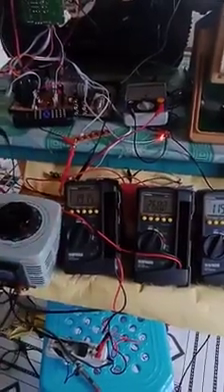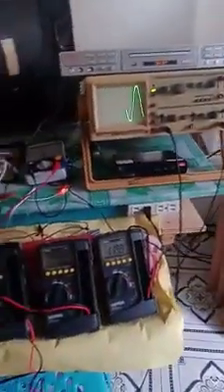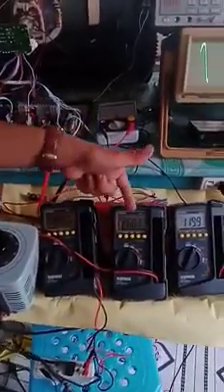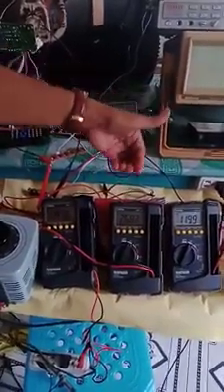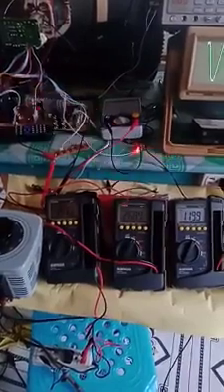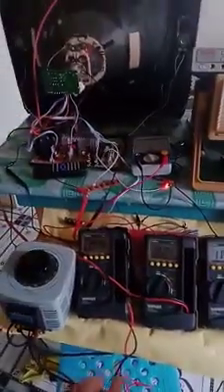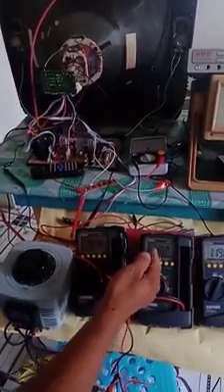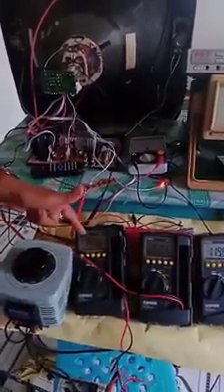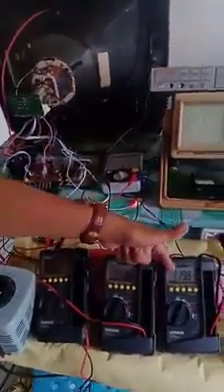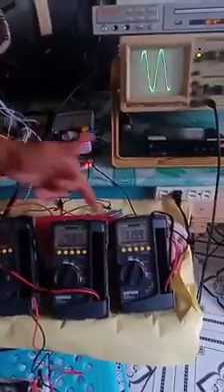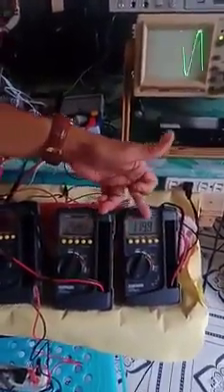Now the AC voltage which is supplied to the TV receiver from the outlet is 197. Then the voltage across the capacitor after rectification is 268. It goes down. A while ago, it was 305 volts, but now the voltage across the capacitor is only 268. It goes down because the input AC voltage from the outlet is lowered down to 197. But look at the voltage at the output of the regulator. It retains the same.